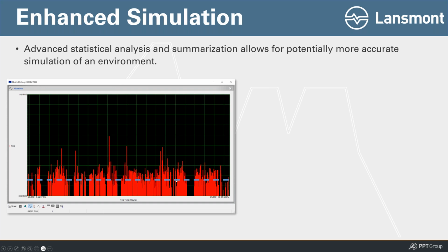If I'm only testing at this intensity, am I at some risk that these types of inputs that happen in the real world could contribute to damage in my product? And just talking about vibration testing in general, there are two things that are generally accepted to have the potential to cause damage. One is the time exposed to vibration, how long something is exposed to vibration, and the amplitude. So how severe is the amplitude? So it's time and intensity. Both of those things contribute to damage.